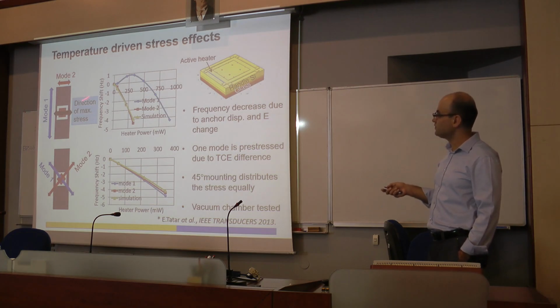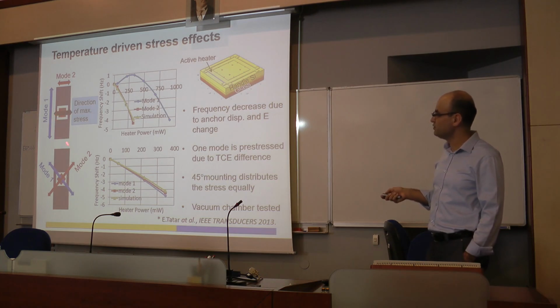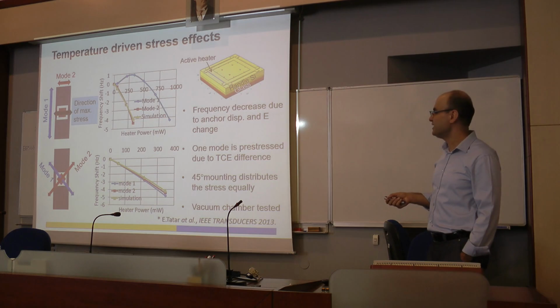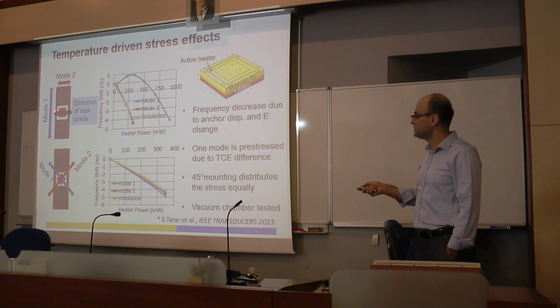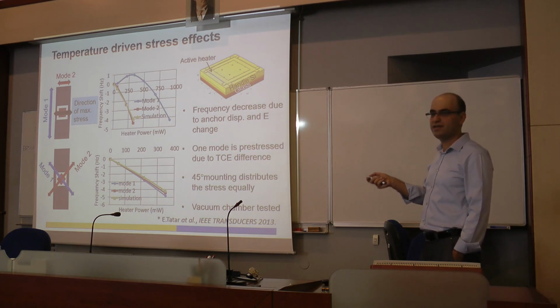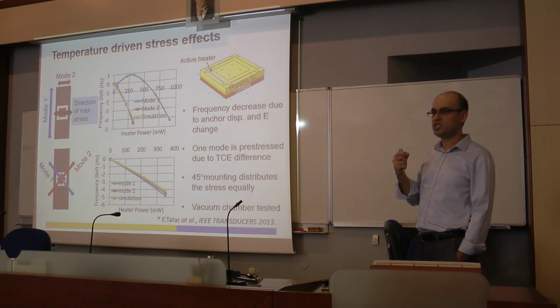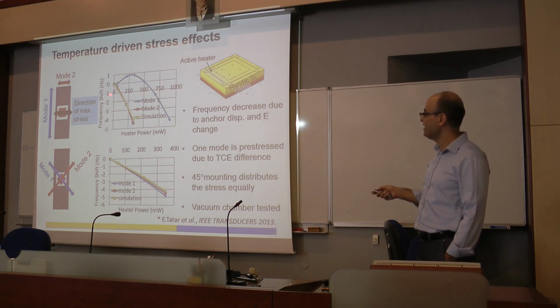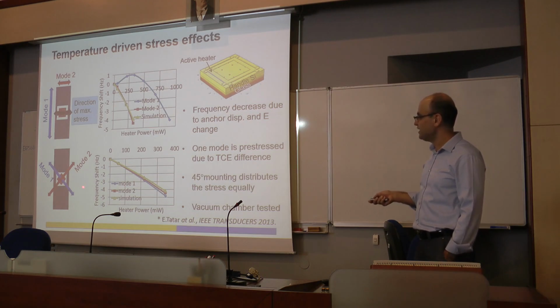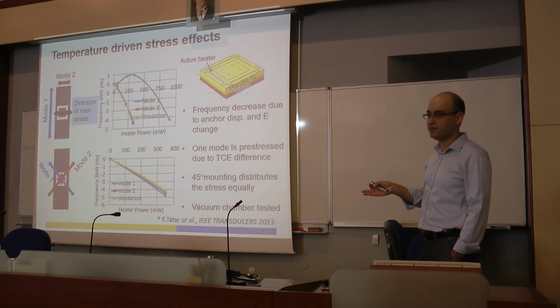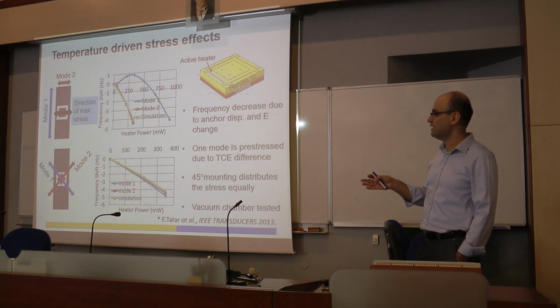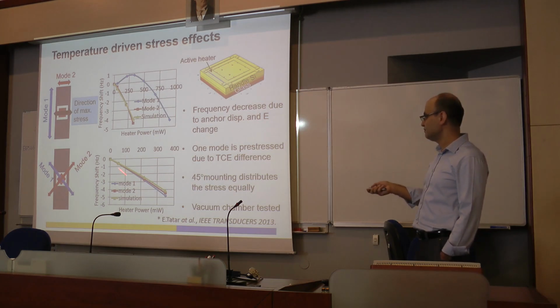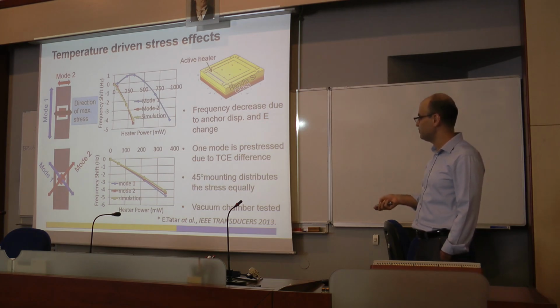So this turned out to be the stress effects that I mentioned to you. Since this ceramic package, the one that I use, is a long rectangle, it ends up being a different stress on X versus Y. And that pre-stress conditions the device in a certain way, which results in this response. But when you rotate the device 45 degrees instead of mounting it straight, then you get a match between whatever you're doing.